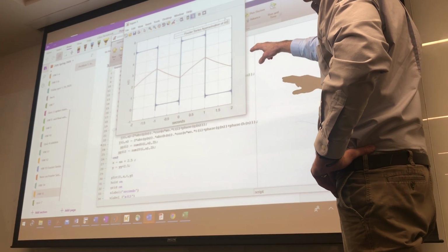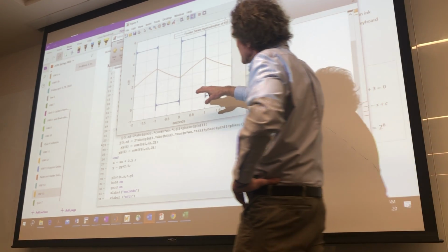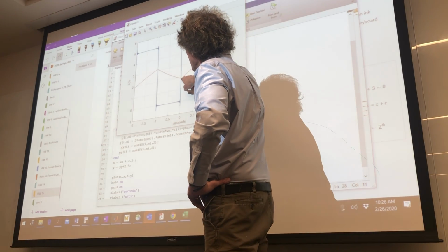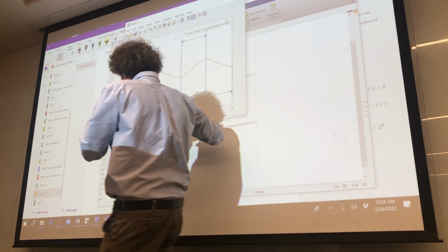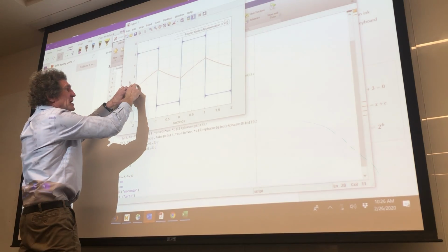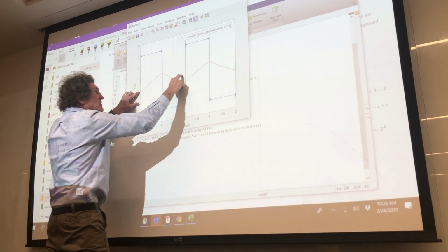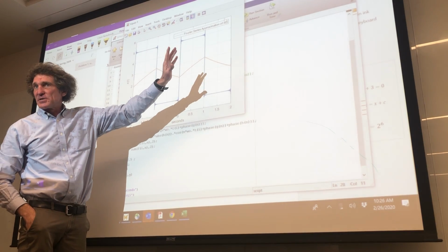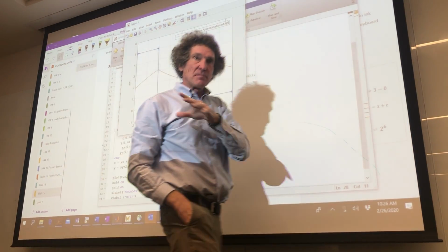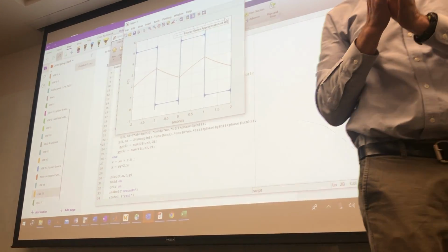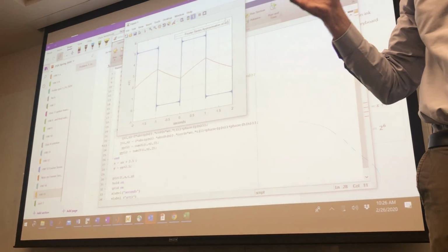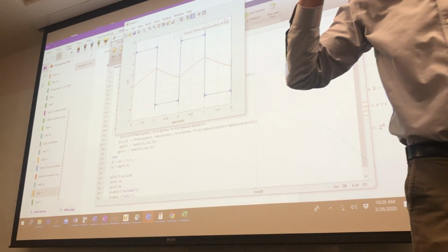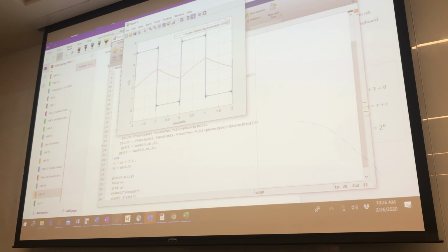So when it goes from the high state to the low state, now this is the average current. And let me tell you one other thing about this. What you have basically is some average value here, the 2.5 that this thing is riding on. Now if I change the value of the inductance, and I'm going to do it in my program, you can see that as the inductance gets larger and larger, those ripples go to 0. Let me do it for you and you'll see this.